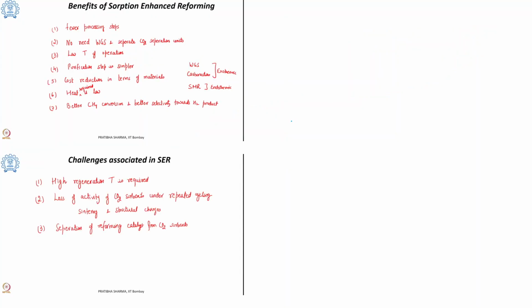The benefits of sorption enhanced reforming are listed here. You can see this is fewer processing steps. There is no need for water gas shift reactions in an extra unit. All of this occurs inside the reaction chamber or reactor.